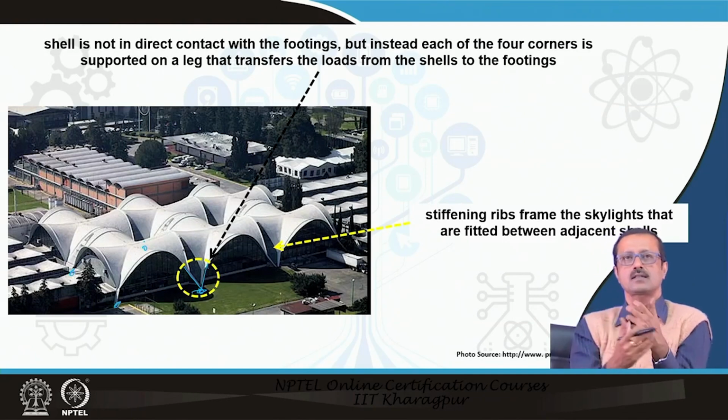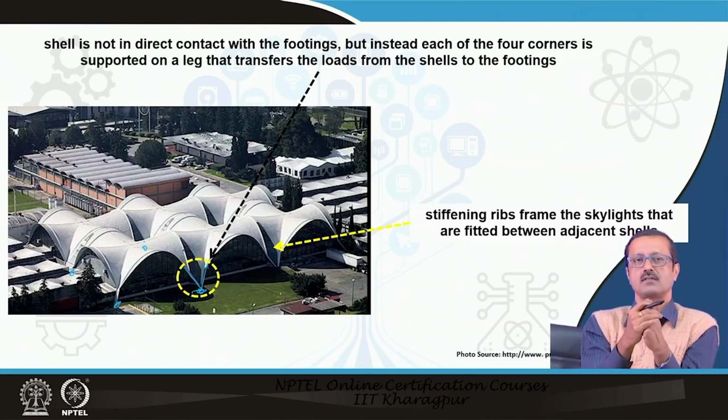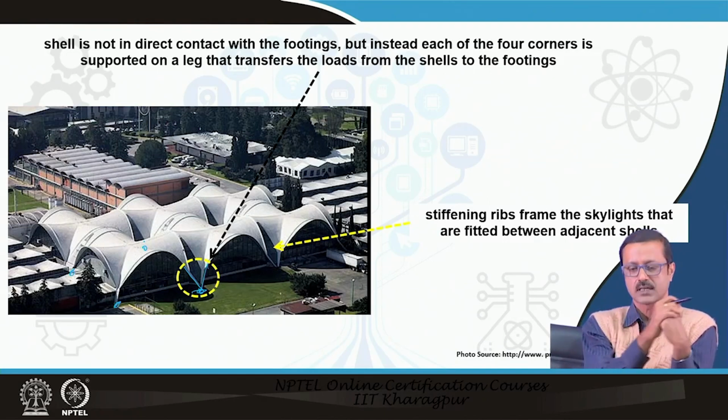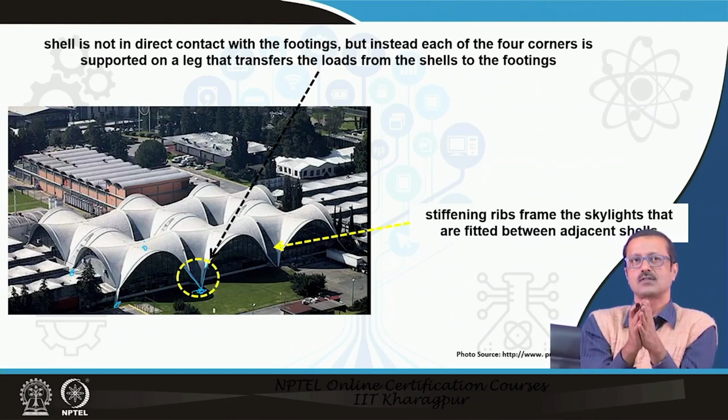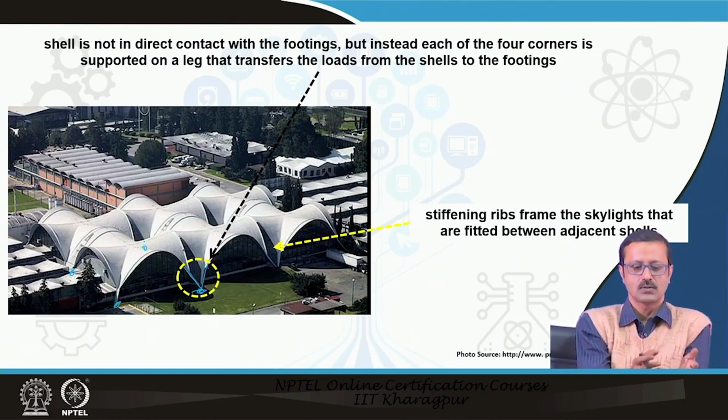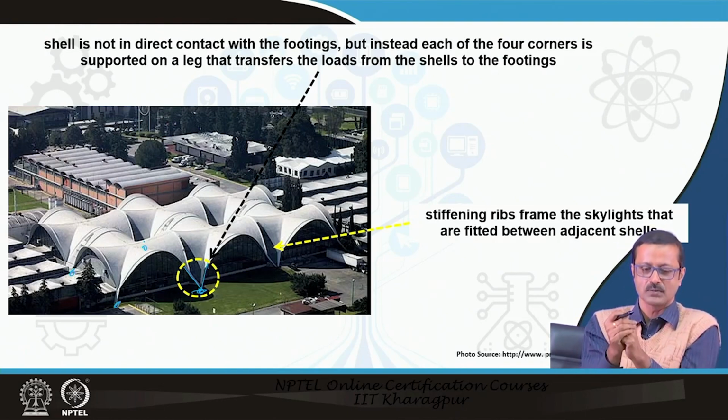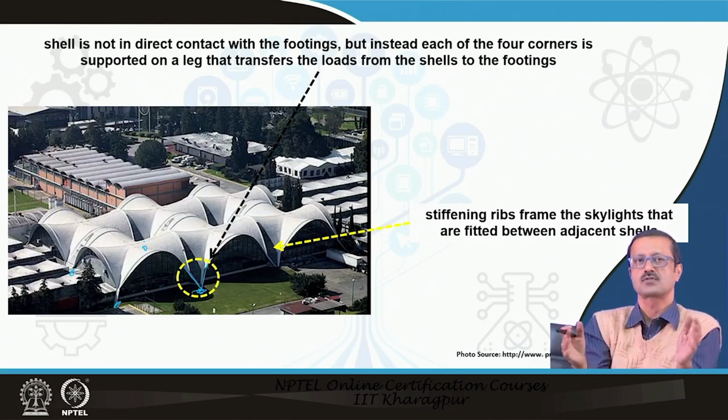So, in the industry, as you know, you need long span areas for movement of the trolleys and maybe some kind of equipment, goods and all. So, as much as we go for the reduction of the columns, the reduction of the structural footprint, it could have been a nice way to take care of the structural system in such a way that the 26 by 26 meter span is almost freestanding and has no obstruction at all, which is definitely welcome in industrial architecture.